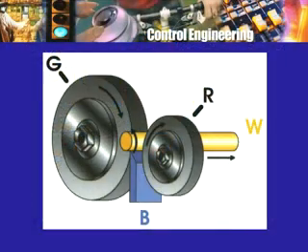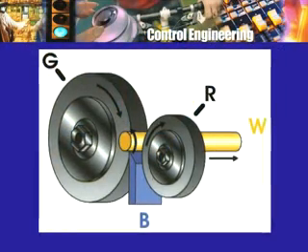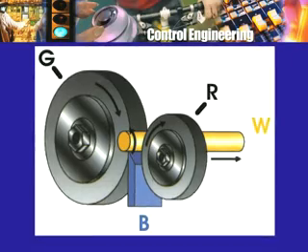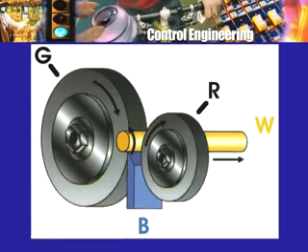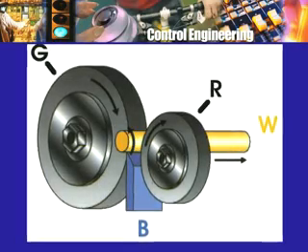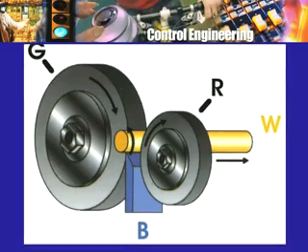So how long will it take for the motor to build up its speed, so that then I can connect the load and my grinding will start? Remember, the grinding job usually will not start with the grinding wheel at rest. I will have to put the grinding wheel into motion and then only bring it close to the job and start my grinding operation.